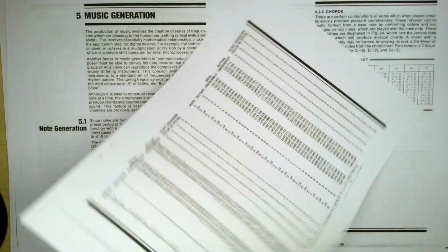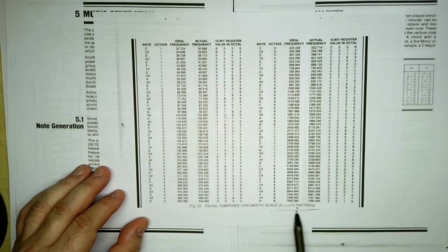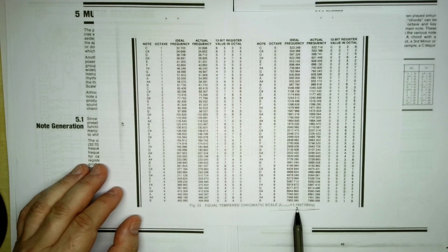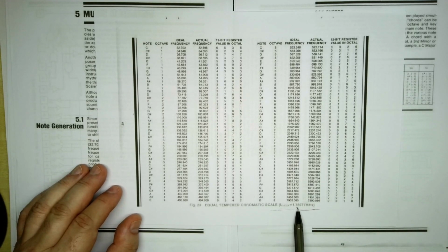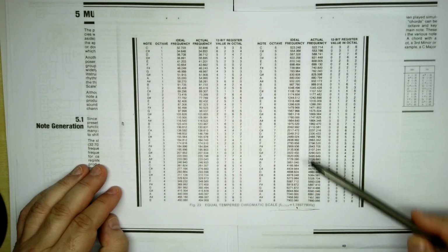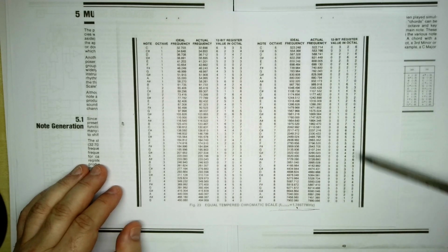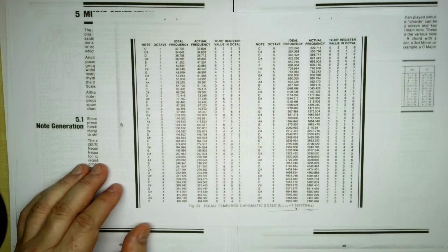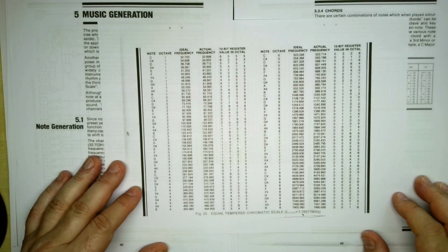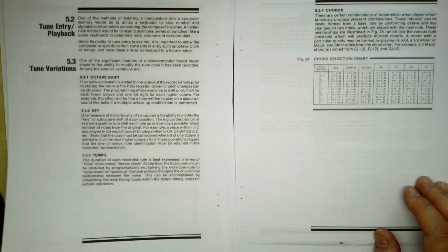Then as far as the music generation is concerned, there's a useful table here. This is based on the clock frequency of the 3.57 megahertz TV clock crystal, which tended to be used in a lot of early computers. And so this shows all the different notes we can get based on that frequency and what the 12-bit octal values are in the configuration registers for each note. So we'll have to generate that table for whatever clock frequency we choose, and then that should allow us to convert music into the configuration needed for that. It also includes information on how to do chords, which is good.